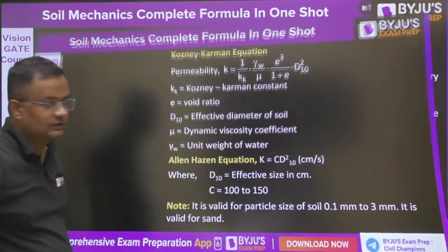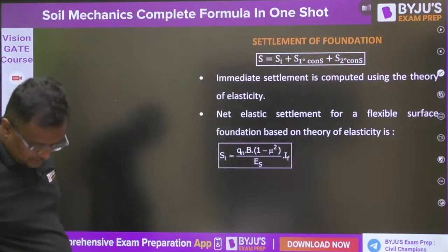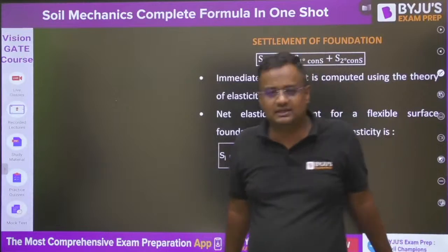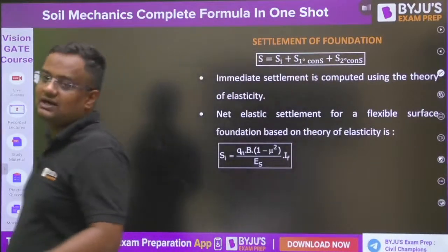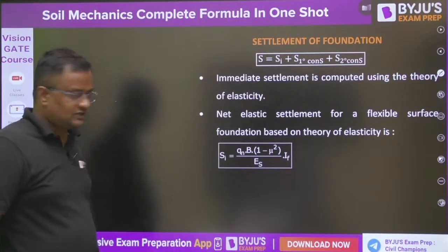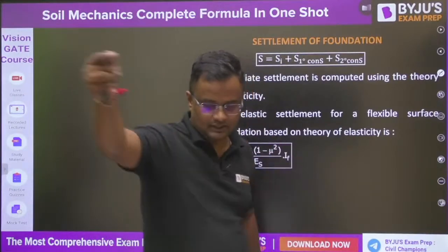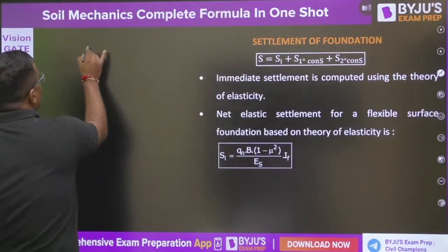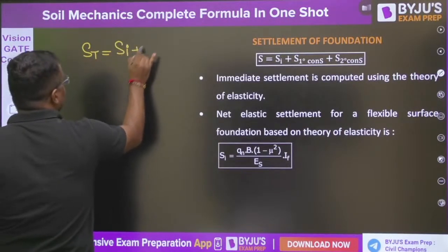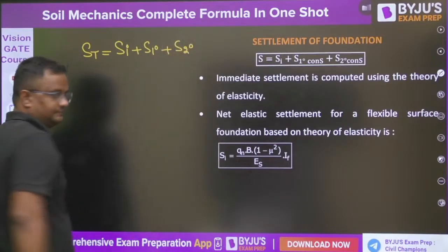Okay. So this is for the same size of soil. Now let us go to the consolidation. Guys, vertical stress, I'll provide you the notes, not taking it here, because every formula there is empirical, either the Newmark chart, Boussinesq, Westergaard, all of them. Now the total settlement of a soil is S, that is Si, the immediate, plus S1 degree plus S2 degree.